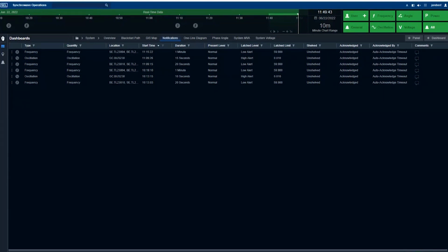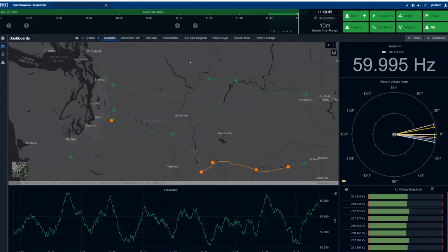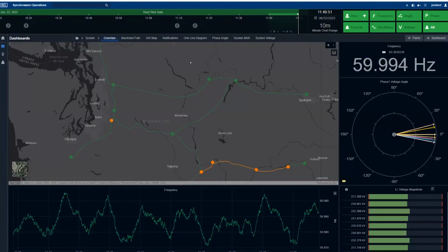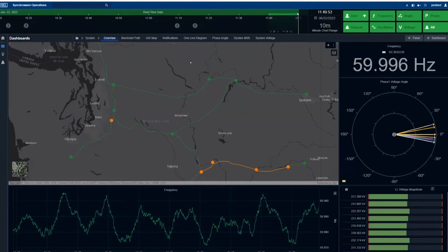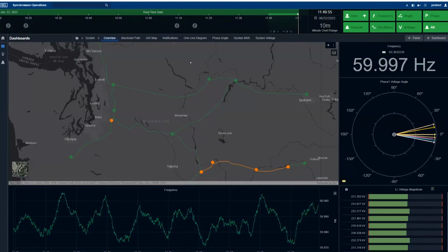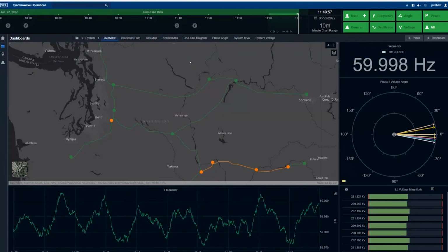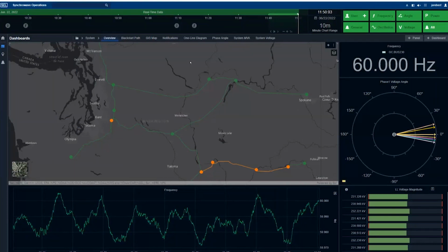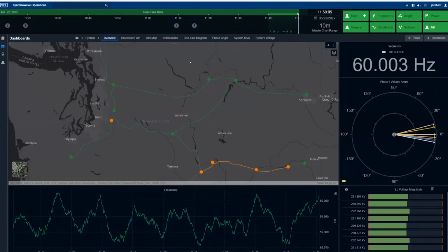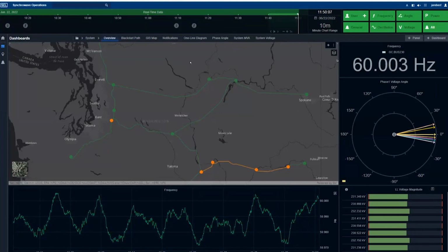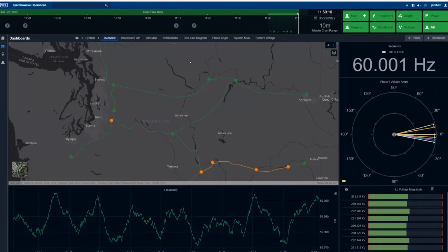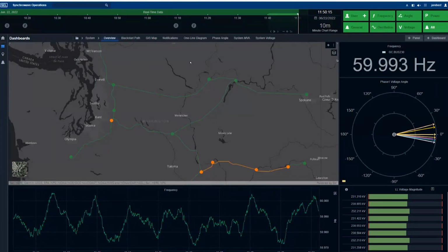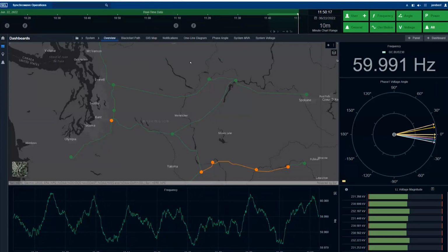Okay, and then I've got a couple of specific ones here, Jared, on the PT failure that maybe I can take. The first one is, for this PT failure detector, do you need 30 or 60 messages per second, or what is the minimum rate needed? We support 30 and 60, and then in Europe, 25 and 50. But we currently do not support lower than that. Of course, it gets more challenging the lower the rate goes, because fast-moving changes get filtered out.